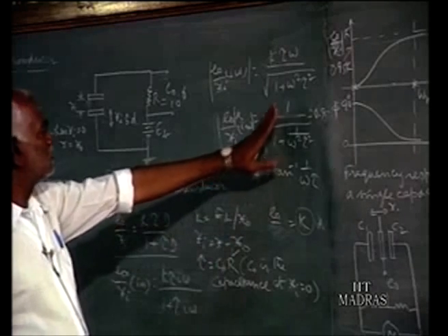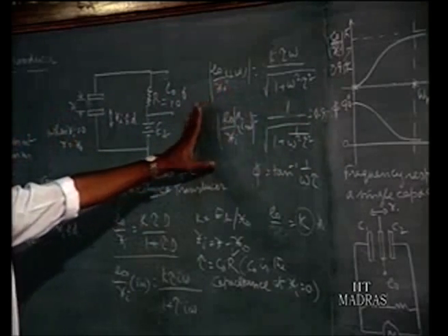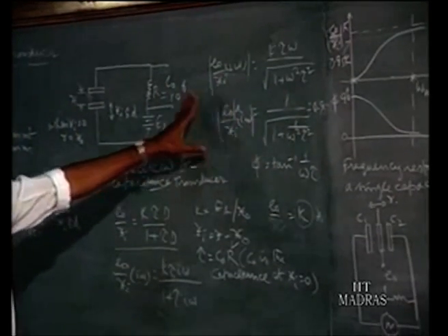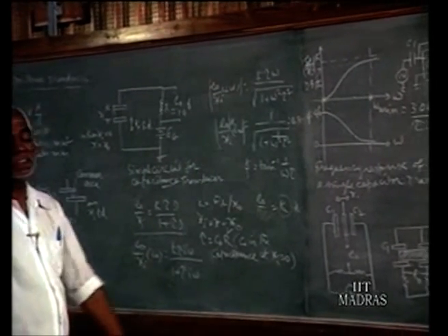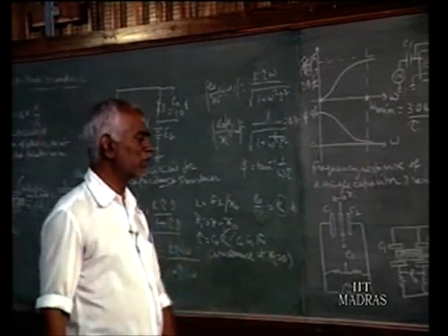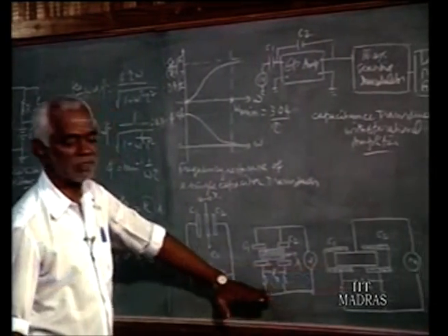So, the simple circuit with one capacitor has this drawback: it cannot be used for static measurement. If you want to use the capacitor for static measurement, then we go for bridge circuits with capacitors, AC bridge circuits with capacitors. Three such constructions are shown here in this figure.